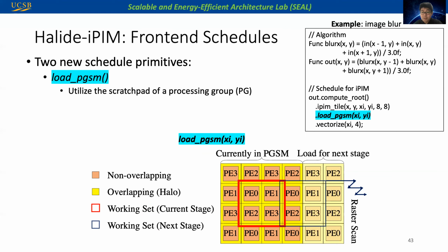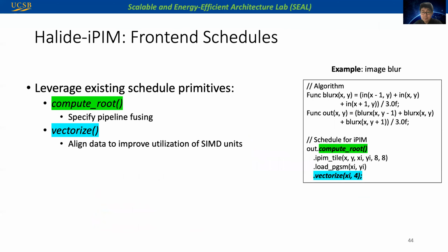This schedule specifies that before computation starts, every PE inside the same PG should load data from the local DRAM banks to the shared PG scratchpad memory. We also preload the working set for the next computation stage to hide memory access latency.